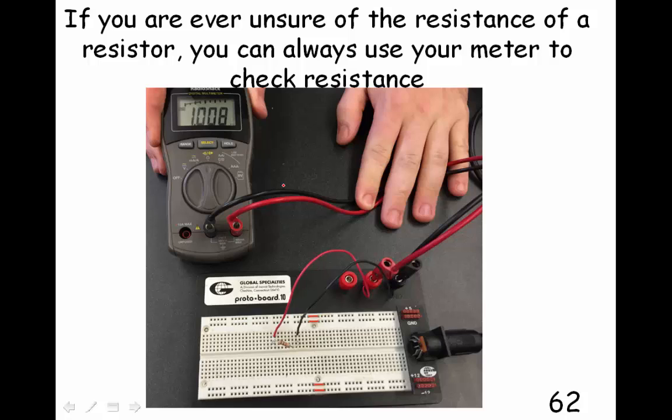If you're ever unsure of resistance, like if you're not good at measuring the color code, which I've done electronics all my life and I still don't know it, I just use a meter to check the resistors, and this one is at 1K. And it's actually better than the color code because it gives you the resistance to 4 significant figures. And each one of these resistors will vary according to its resistance.